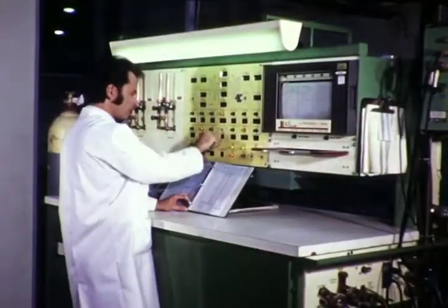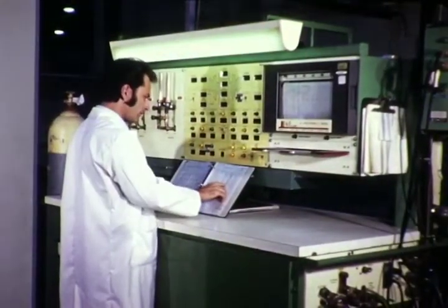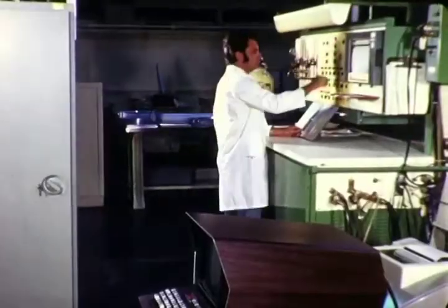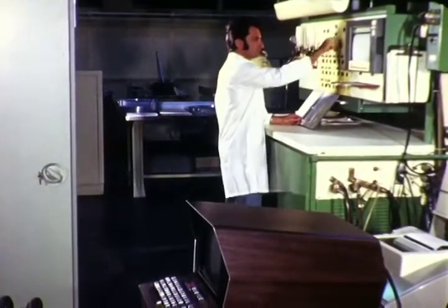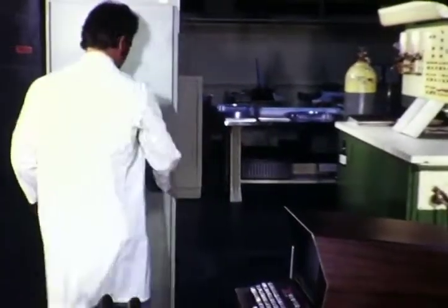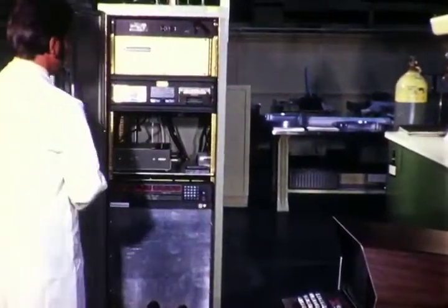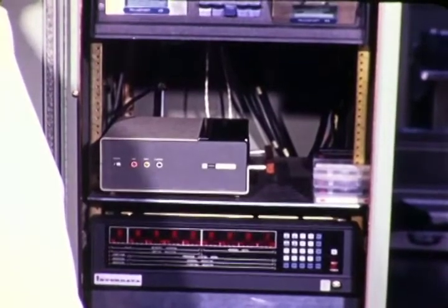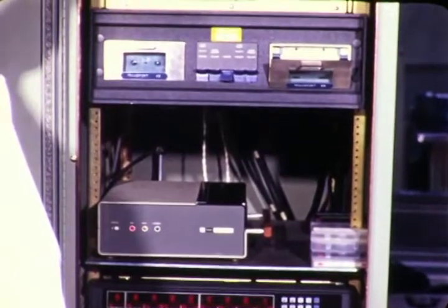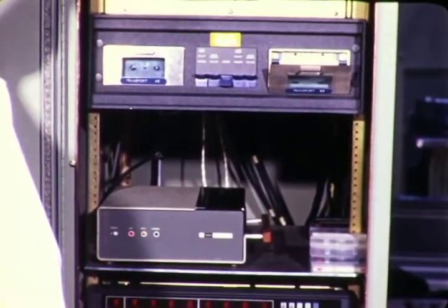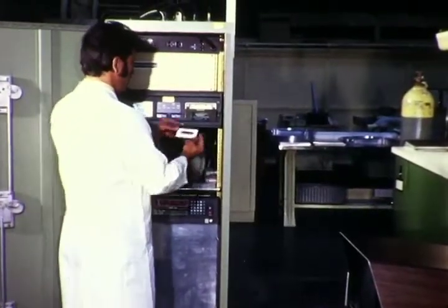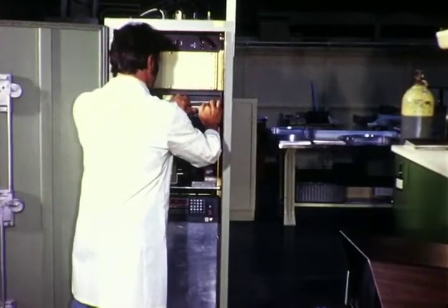The welding power supply is a 400 ampere high-frequency pulsed arc, combination TIG-MIG unit. The operator sets the digital controls to the welding schedule. An electrically shielded cabinet houses the computer, telephone coupler, tape recorder, and interface modules. The 16,000-byte mini-computer controls the welding process directly, but must first be loaded with a program provided by the magnetic tape cassette.